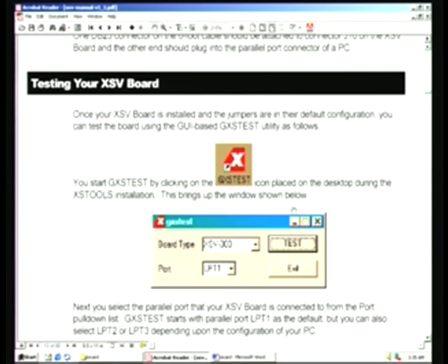The first thing is, when you connect the board, the board connection is quite simple. The FPGA board is connected by cable to the parallel port, and can be connected straight away to LPT1 or LPT2, any parallel port on your host system. In addition to the power supply, that is the only connection that you really require on the board, and we will be seeing this later on.